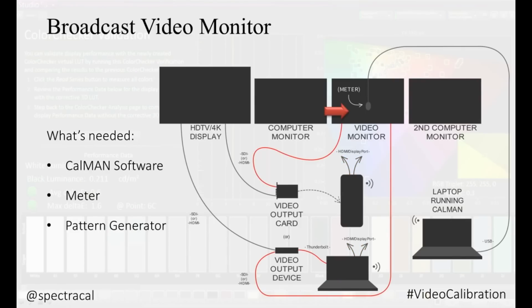For video monitors, most of them have some sort of basic calibration controls, typically not as many as an HDTV or projector. And these displays are usually pretty linear in color, so you always want to check some of the preset modes in the display before doing any calibration to find a preset that is closest to the color standard you are targeting. Oftentimes you can find a preset on these monitors that is really close without having to do much internal optimization at all.